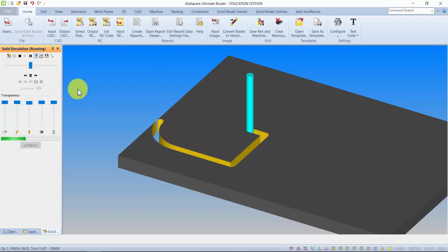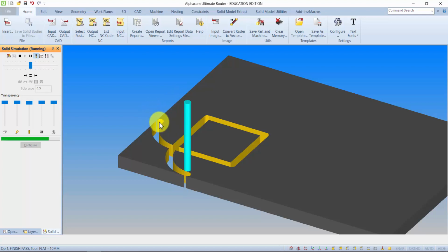And you can see what it does there. It starts and it enters the workpiece over here. So if there is any vibration or any reason for it to move here, it's only going to damage or deform this waste piece of material. It'll enter the workpiece there, and then it'll not stop moving all the way around until it gets to the exit point, and then it'll remove itself.